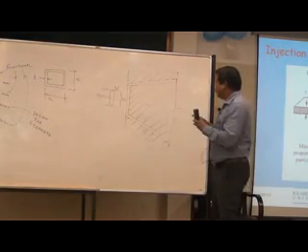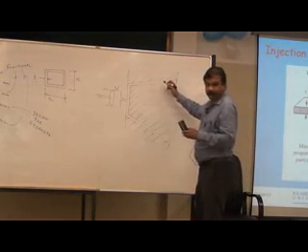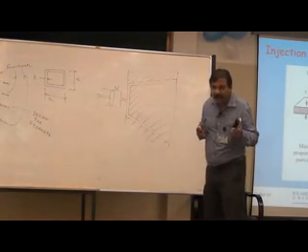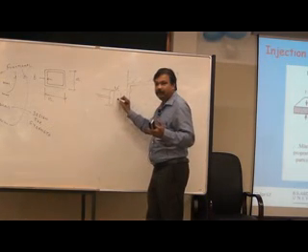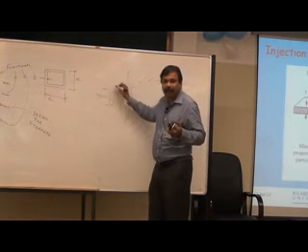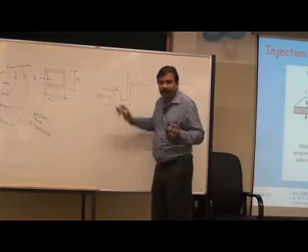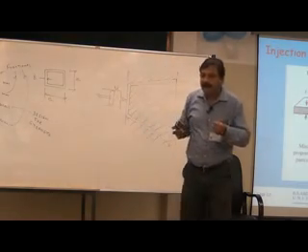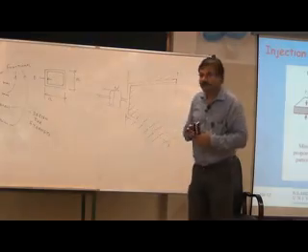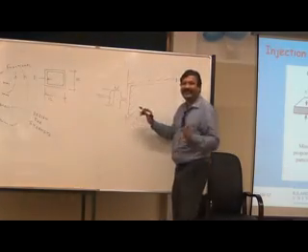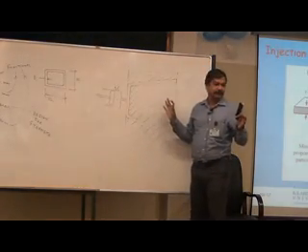Okay. So this cavity is the shape of the bucket. Now here you have a piston. You have the molten polymer entering in, and the molten polymer is pushed inside. The molten polymer is injected inside.